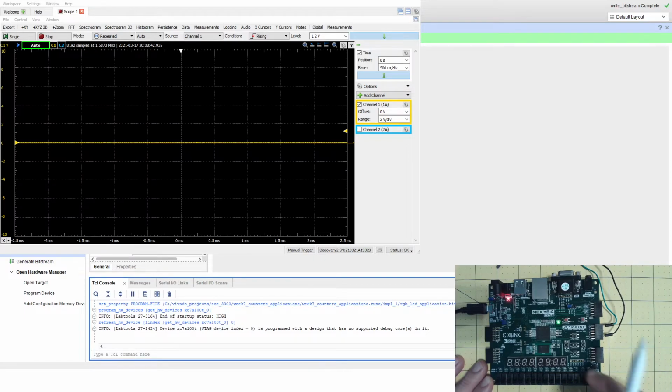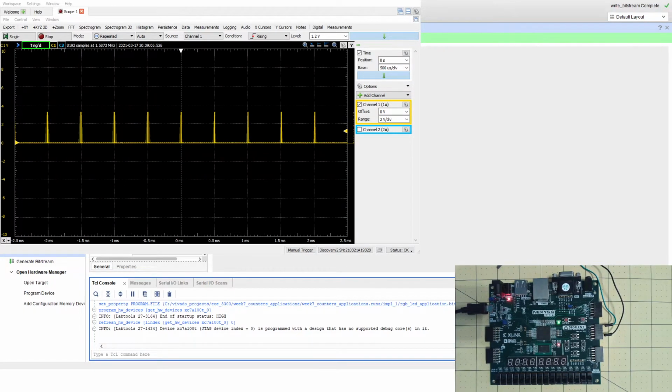So what I can do is technically just turn it on a little bit in here. So I'm going to basically put the number 3. The duty cycle will be 3 divided by 256. And once I push that middle button in here, it will write it to the register that is storing the red color. So I'm going to do that in here, and you can see the red color is now on. It's very subtle, but it's on, and you can see here on the timing diagram that it is on for a short period of time.